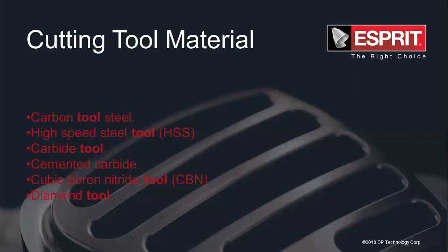So that's why this carbide tools has been manufactured with the help of powder metallurgy techniques, and it works 4 to 6 times faster than high speed steels, as well as it has high compressive strength, but they are brittle in nature and can't withstand the impact load. So as per requirements, this carbide tools has been used.